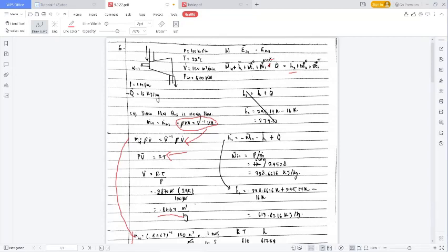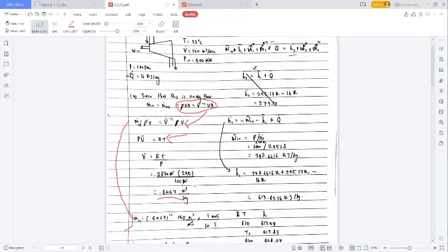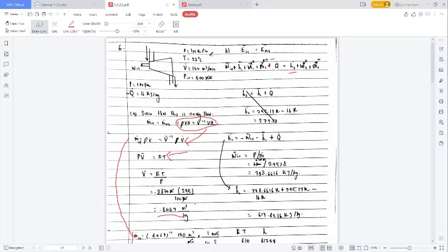Since there is no elevation, we can neglect the potential energy. And if you make an analysis for a compressor and turbine, people will usually just ignore the kinetic energy. It is because the value of kinetic energy is too small, so it brings an insignificant change to the final answer for the energy equation, so we just neglect it. But in this case, it is also because the question doesn't state the velocity for the air, so that's why I'm neglecting it.